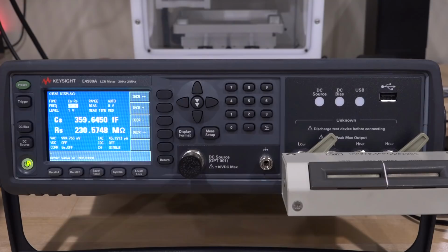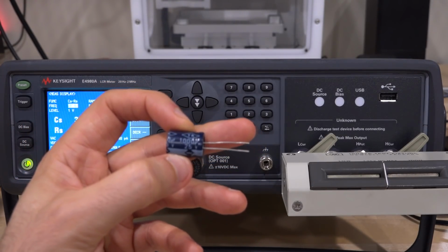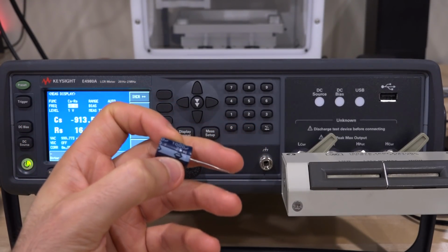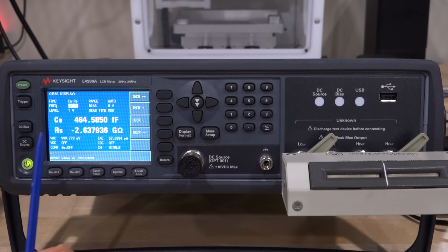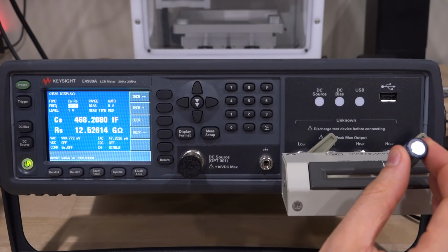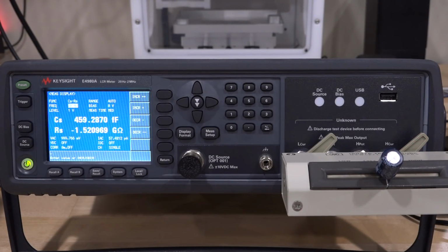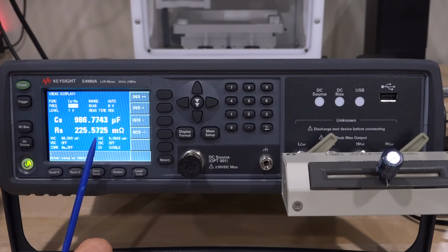Let's plug in this capacitor. This is a 1000 microfarad, 25 volt capacitor. We expect it to have a very good ESR, so I've already changed this to measure RS, which is a series resistance. Let's go ahead and plug it in. Of course, the orientation doesn't matter because this is an AC signal being applied. Let's see what we get. There you go, 986 microfarad, 225 milliohm. So it's a good, healthy capacitor with a good ESR, and the value is very close to where it should be